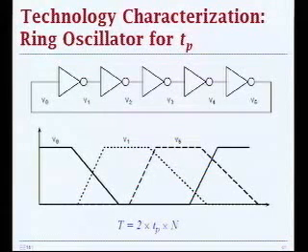For example, you would likely have fan-out higher than 1, and you will have more complex functions to implement than a simple inversion. And you may also want to have a chain of gates to implement something useful. So typically, you have about 20 to 50 times less for a clock cycle than provided by this inverter chain.